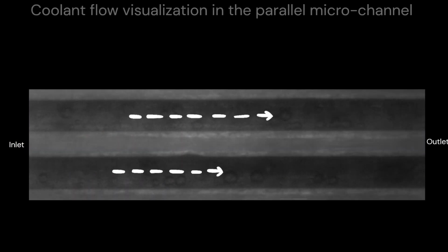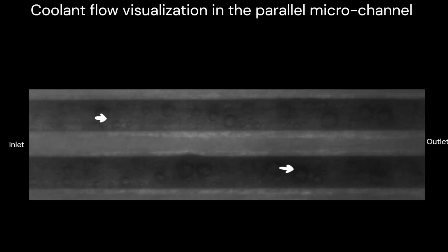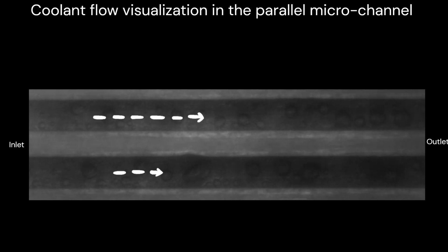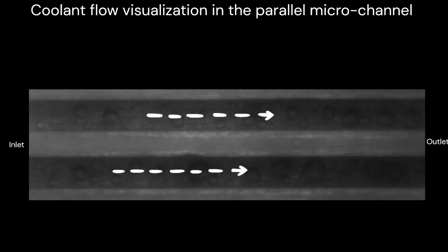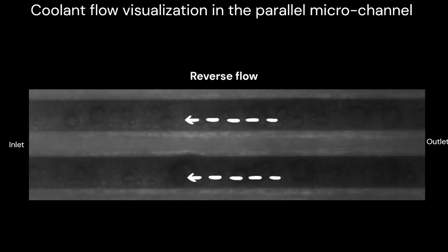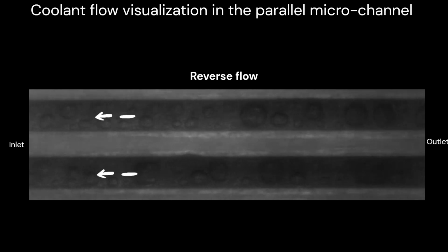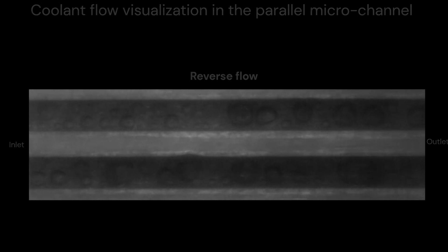High cooling performance can be achieved through phase change heat transfer, particularly when the refrigerant reaches its boiling point at the heated surface and generates bubbles. However, the bubbles within the channel act as a resistance, impeding the flow from progressing downstream and causing inlet backflow.